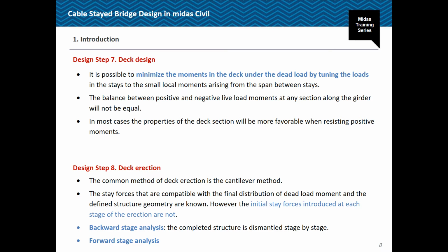Regarding the construction stage, the common method for deck erection is the cantilever method, which is very common and quite convenient in terms of saving temporary works and allowing for the construction itself. The stay forces that are compatible with the final distribution of the dead load moments and the defined structure geometry are known. However, the force at each stage is not known. That's why construction stage analysis is required.